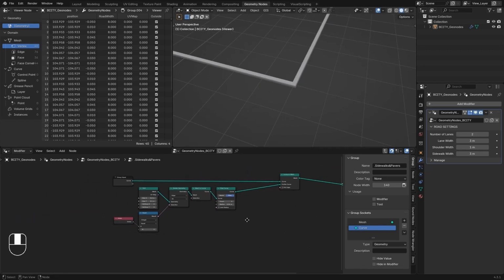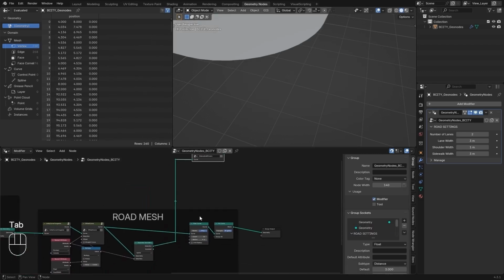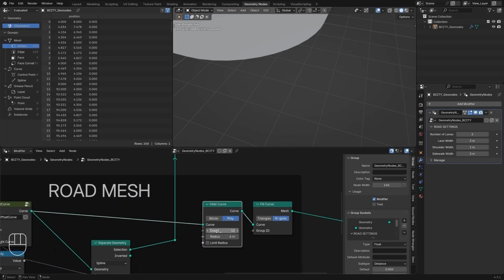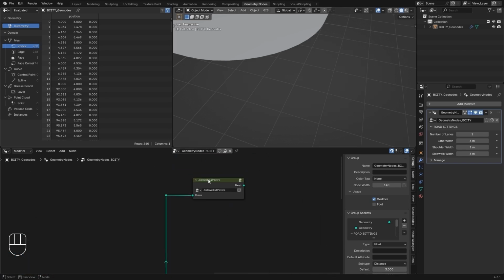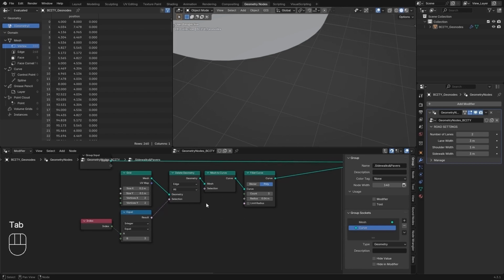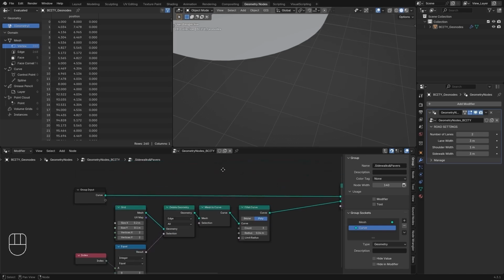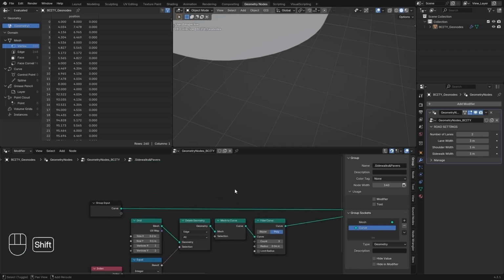Looking at what we have now, the curve has been skinned correctly. However, we're still getting a sharp edge, so we'll need to add some rounding, just like we did for the road mesh earlier. Previously, we used a segment count of 12 and a radius of 4.